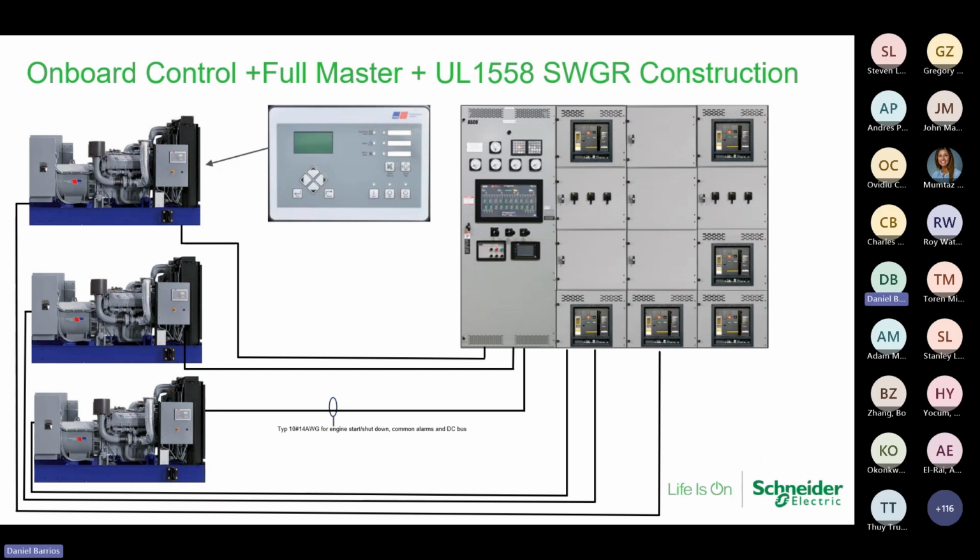When you look at MTU, MTU has typically come to ASCO to assist them with this type of product. They will use our master control section and distribution section, and all of those tie in, but you are still relying on the generator set in order to be able to do the paralleling. However, notice now by coming into an ASCO section, those tiles, which we will show you in much greater detail, are there for your NFPA annunciation of alarms and shutdowns.